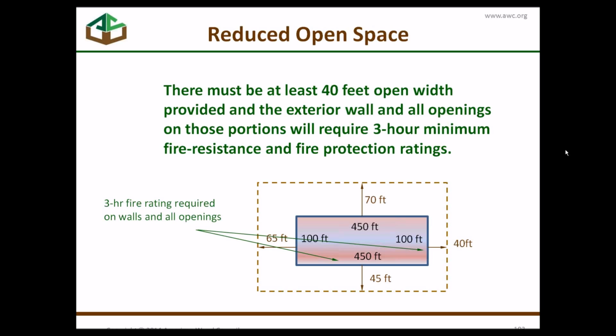If you're measuring at right angles from your exterior wall, I can see how it might be tough to do a weighted average because it's changing infinitely along that line, isn't it? Yeah. So I guess what you'd have to do is take an average there. The width would be an average between your narrowest and your widest portion. And check with your code official to see how he wants you to do it.